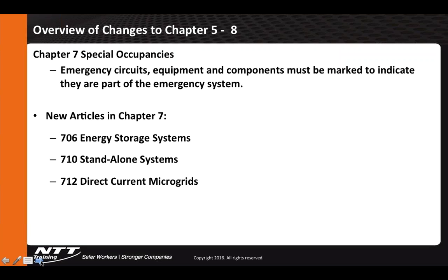We also see some other changes, that term extra duty cover. We talk about, in a wet location, you've got to use that extra duty cover and so forth. We now actually have a definition in Article 406 on receptacles for what an outlet box hood cover is, and they've clarified the information in 406.9 on use of that extra duty cover.